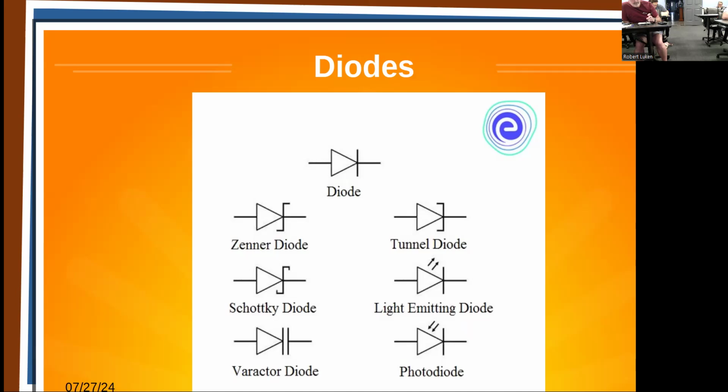And then you have a photodiode that's the opposite, where it allows light to come into the p-n junction and actually create a potential. And that's true for any diode also. If you were to expose the p-n junction, it would be affected by light. They do the same thing with a phototransistor, where they put a little clear lens where light can get onto the base emitter junction of it and create that voltage potential.